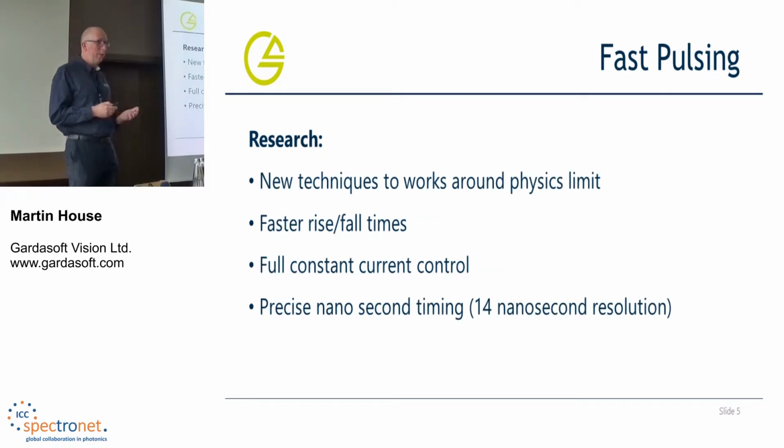So we did quite a lot of research looking at different techniques into how we could achieve this fast rise time with a fast pulse. And typically when I'm talking fast pulsing, I'm talking pulsing in excess of 50 kilohertz, and quite typically in the area of 100 kilohertz. I know it's quite common now to have line scan cameras of the order of 300 kilohertz. But it very much depends on what your application is.